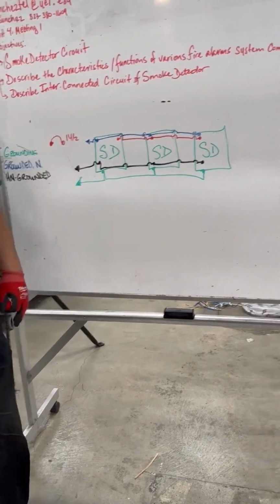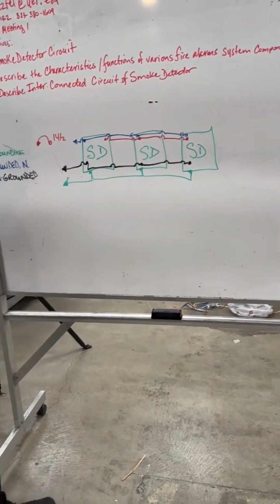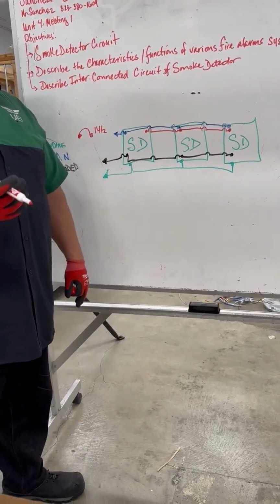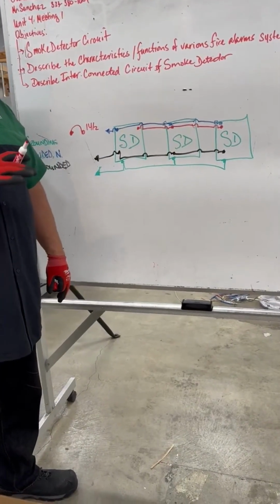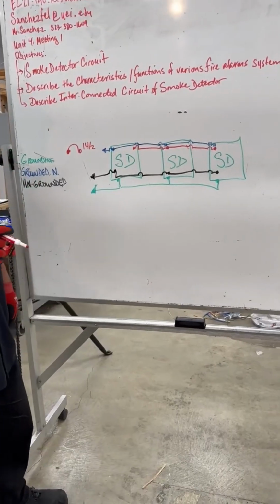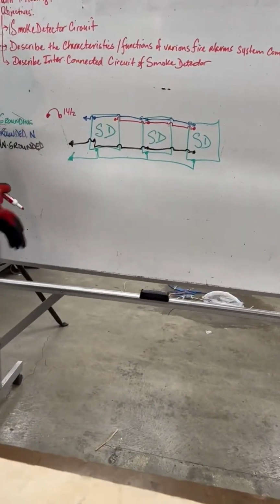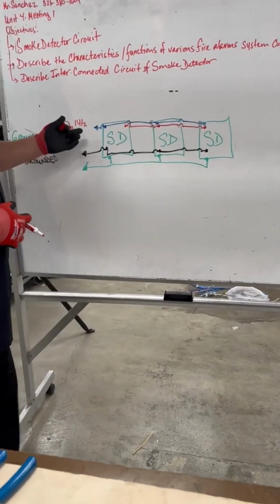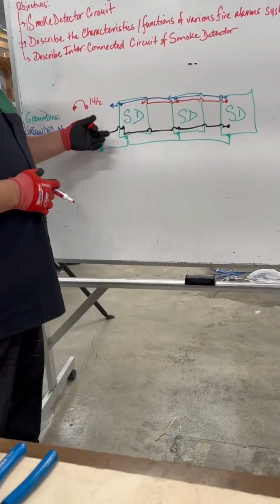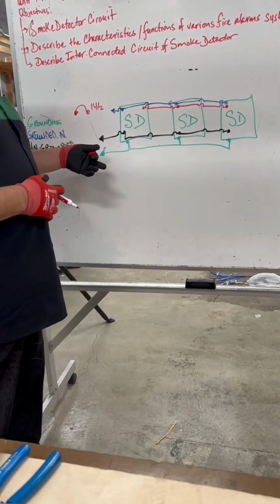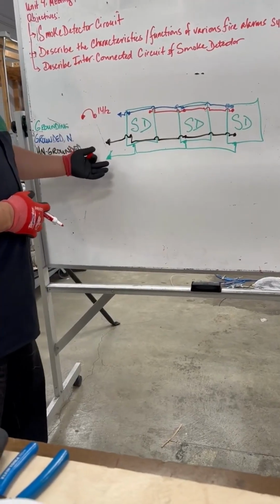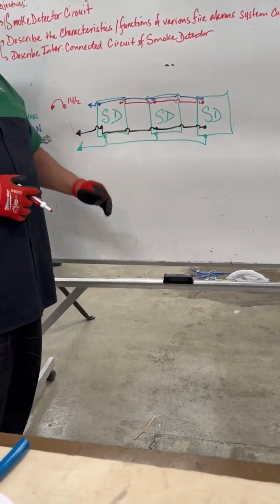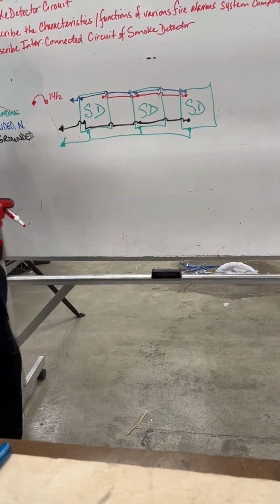I have seen in some installations where you can actually purchase a circuit breaker that is red in color, specifically designed just for smoke detector fire systems. But other than that, a label works fine as well. You have your 14/2: your hot, your neutral grounded conductor, your ungrounded hot, your grounding coming in. Then in between our smoke detector circuits, we have